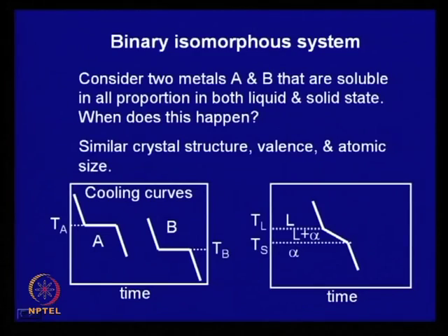So, all alloys are made by melting and mixing, and when you mix, apart from diffusion, you can stir the metal, since diffusion also depends on the state of matter. In liquid, the diffusivity is much higher. So, therefore, mixing is much faster, and once they are mixed in all proportion, you start cooling that alloy made up of A and B.